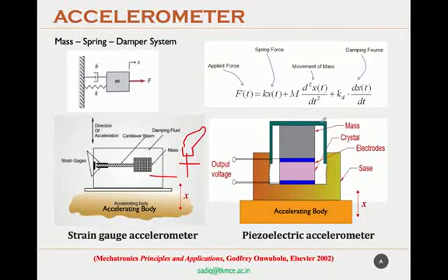Now, in the construction, the spring steel cap will be rotated such that it will be tightened against the thread that is shown here. That means when you fix it to the base, the spring steel material will be forcing this mass downwards, and a squeezing effect happens, and because of that the piezoelectric crystal will be experiencing a compressive force. So in the assembly itself, this piezoelectric crystal is preloaded in this case.